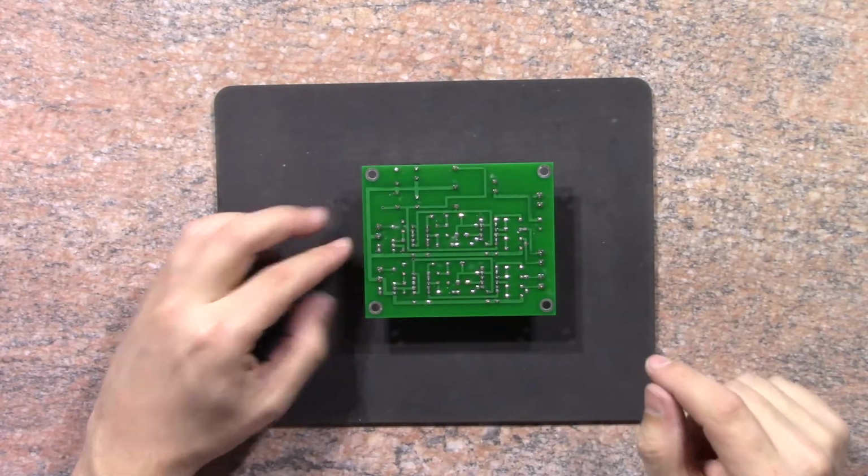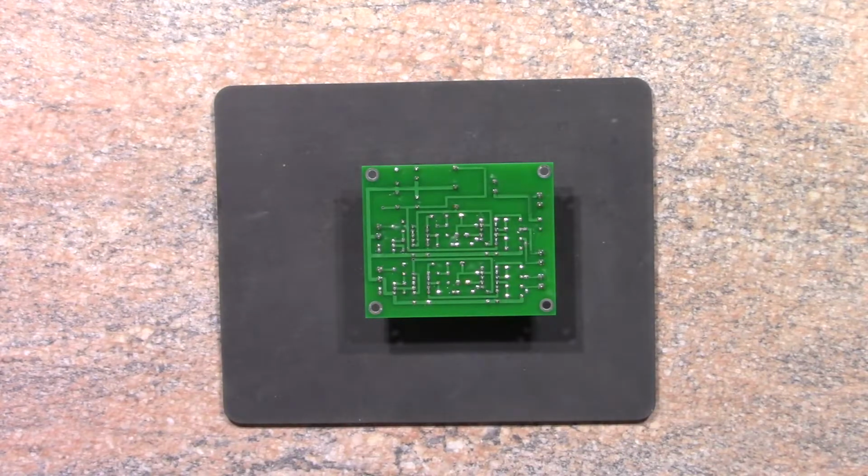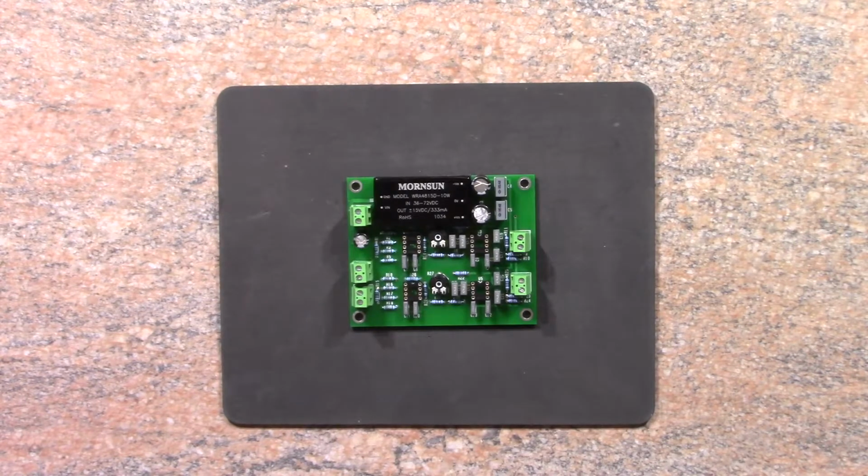Flux is actually slightly conductive, so it's best to clean this off with acetone or flux remover and a toothbrush. I've checked the circuit to make sure everything is soldered correctly, and I've also cleaned the flux off the underside of the card, and all that remains now is simply to insert the ICs and the little dial that adjusts the preamp gain. So the dial simply pushes in.